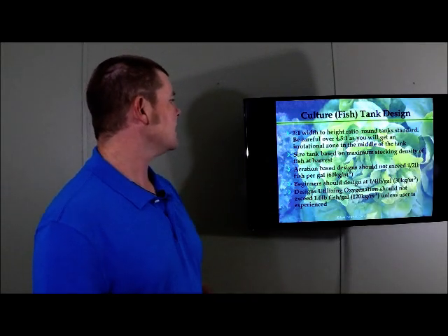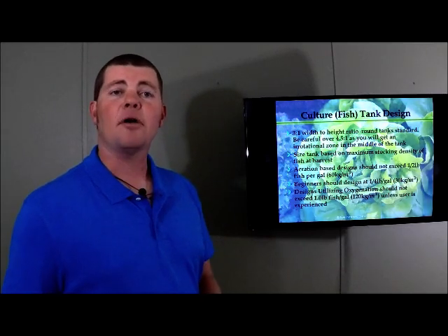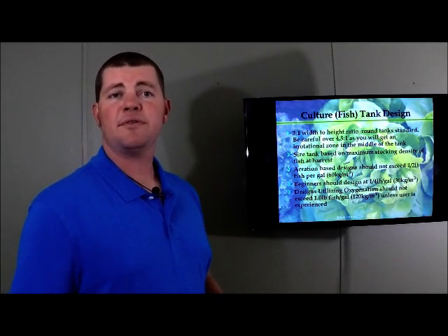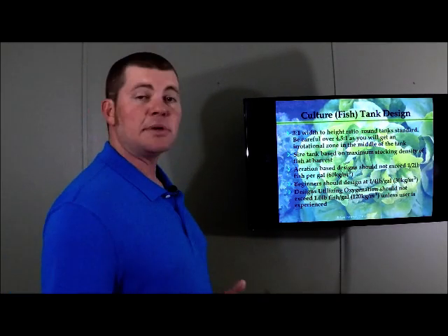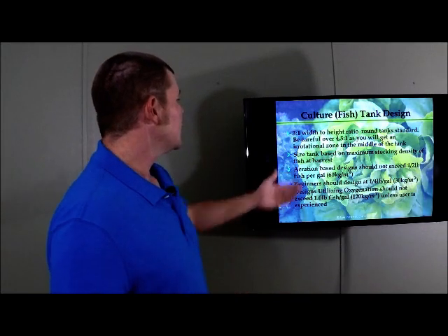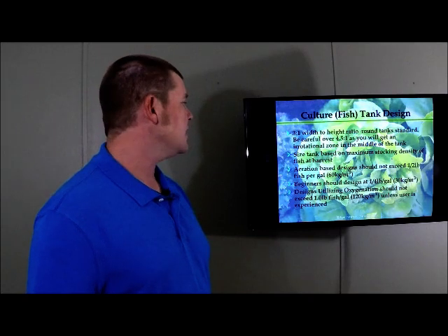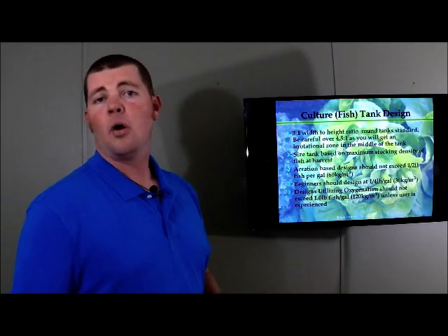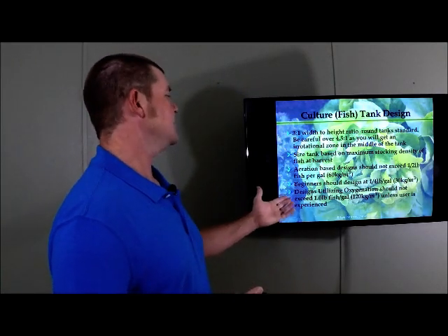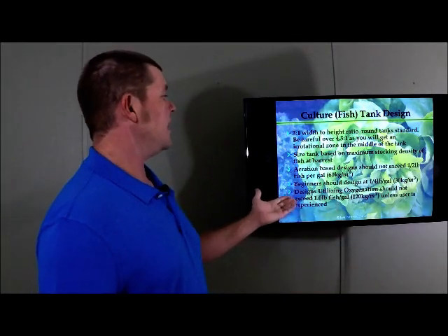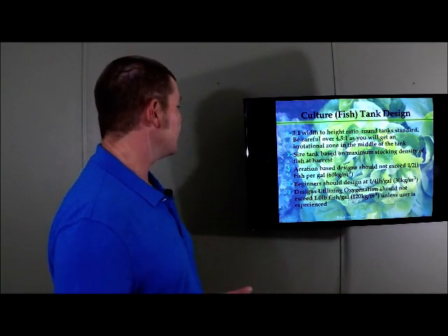We want to size the tank based on the maximum stocking density of fish at the time of harvest. So what is the most fish that are going to be in there at any possible time? That's what we size the tank off of. For aeration-based designs, density should not exceed a ½ pound per gallon or 60 kilograms per cubic meter. For beginners, you should shoot for half of that. Design for a ¼ pound per gallon or 30 kilograms per cubic meter.